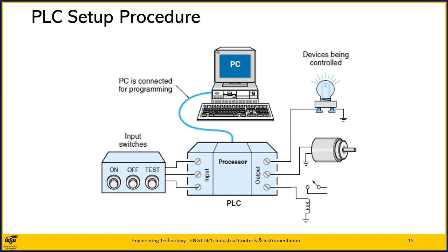The ladder diagram may be entered into the system by either drawing it on a PC screen or using a specially adapted switch box called a handheld programmer. If a PC is used, special software must be installed before the ladder diagram can be entered.